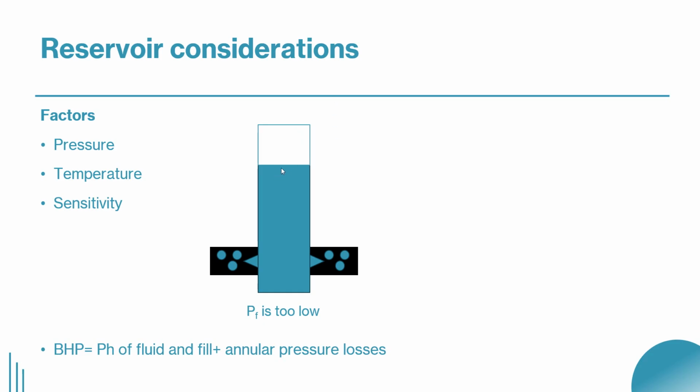So in this case, your treatment fluid or clean out fluid is heavier than the formation can support. You must use a lower density fluid. For example, if you're using brine, you can consider using foamed fluid or staged fluid because it will exert lower hydrostatic pressure on the formation, unlike this heavy fluid. But if you're using the lightest fluid, like foam, and even with foam you cannot establish circulation due to losses or a depleted formation,